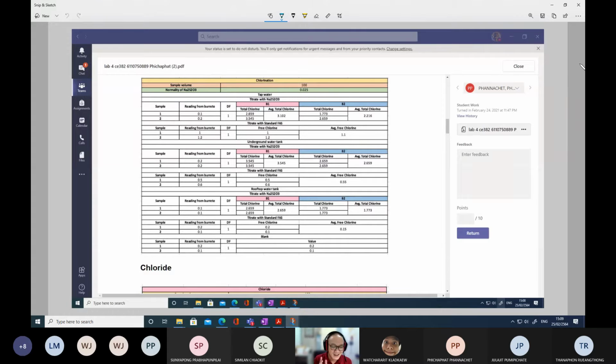We just monitor chlorine. We want chlorine present in water. If it goes higher than 2 ppm, it's okay, as long as it does not go beyond toxicity levels. The recommended values should be in the range of 0.2 to a maximum of 2 milligrams per liter. If you find higher than 2 milligrams, it's okay, as long as it's not 5 or 10. The presence of the chlorine indicates the water is safe from contamination by coliform bacteria or some kind of pathogens, because pathogens will be inactivated if the chlorine is present.